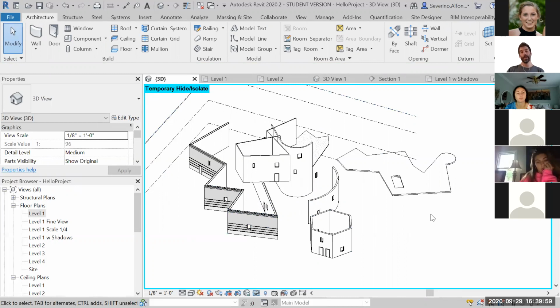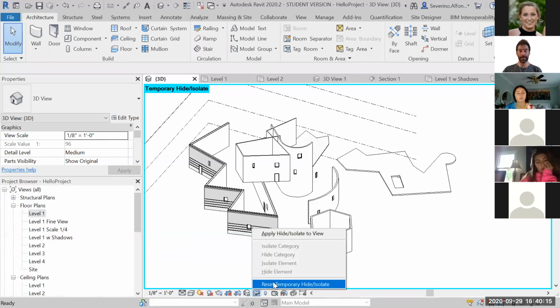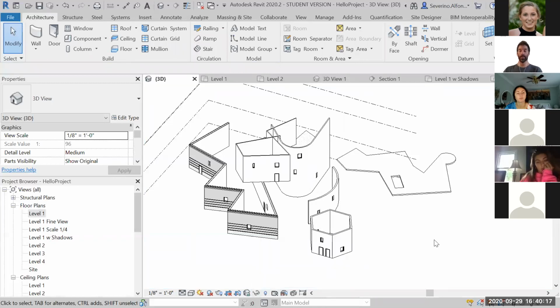And it's recommended that you don't stay in this mode for a long time, that you only use this to work fast on something. You need that wall to be hidden, and then you complete it some other way. When you're done, you click on the glasses again and reset. That will bring the wall back.